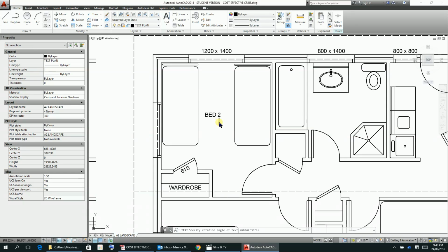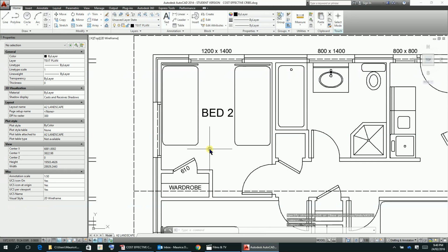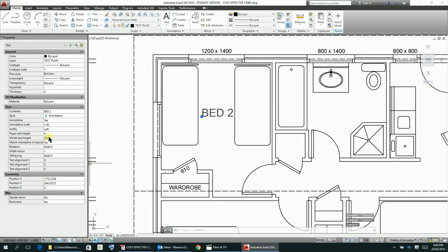Now, because this is just to draw attention to it, I'm going to make it slightly bigger text. So I can select it there, and I can come in here and maybe let's make that 4 millimeters high, or perhaps that's a bit big, and move it around as to where I want it. And I think that possibly is a bit too big, too dominant. So let's hit it again, and let's say, for instance, make that 3 millimeters high. Bit small, possibly. 3.5.